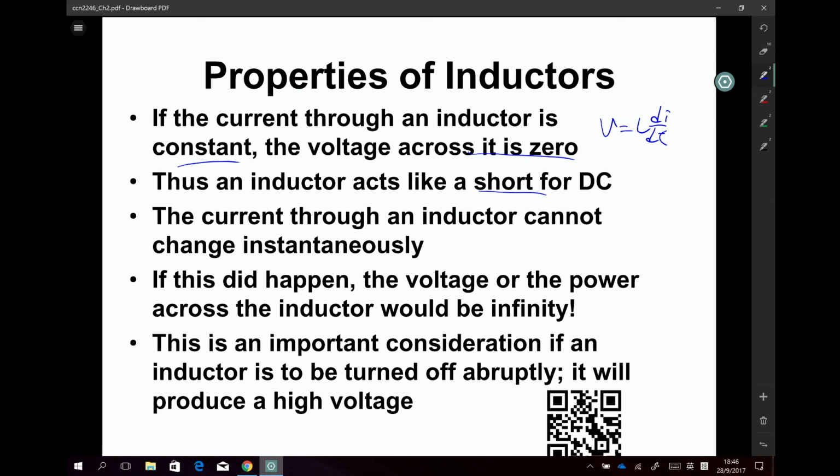Now, just like the capacitor voltage, which cannot make a sudden jump, for the inductor current, we cannot have a sudden jump also. Okay? If I say at the beginning we have 0 amp, and now we jump the current of an inductor to 2 amp. Can this happen? Now we say this cannot happen. Okay?